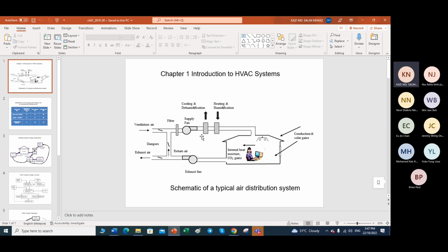But the point is that once the heating, dehumidification and cooling is done there, then after that, if there is variation of temperature, it is being taken care of, and the humidity variation is being taken care of by this heating and humidification, because it has the PLC control system, and then how much the excess air, how much the temperature of the air will be raised passing through the surface of the heat exchanger, and then the dehumidification.